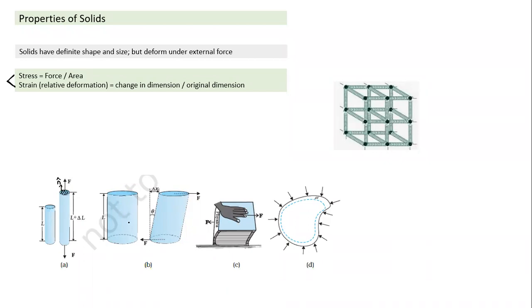The second case is where you can think of a cylinder which is fixed at the bottom. In this case, force is not applied along the area vector. Force is applied perpendicular to the area vector. Whenever force has a component along the surface, this is called a shear force. Force lies in the area. Which area do we divide by? We divide force by the area in the plane of the force.